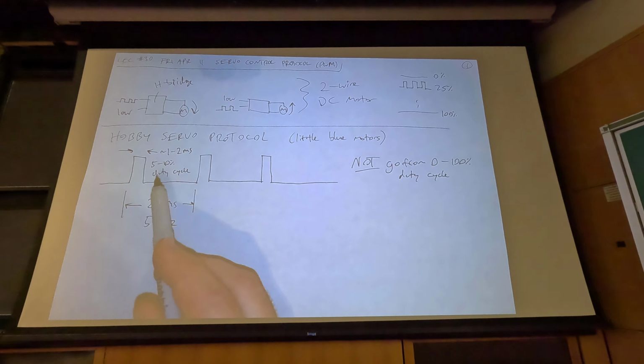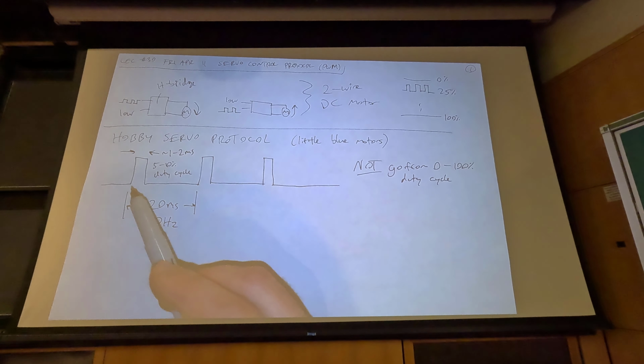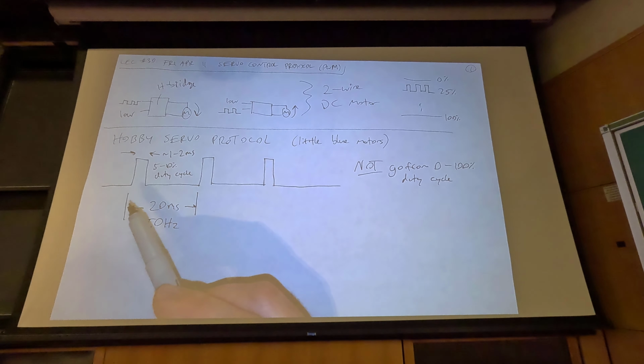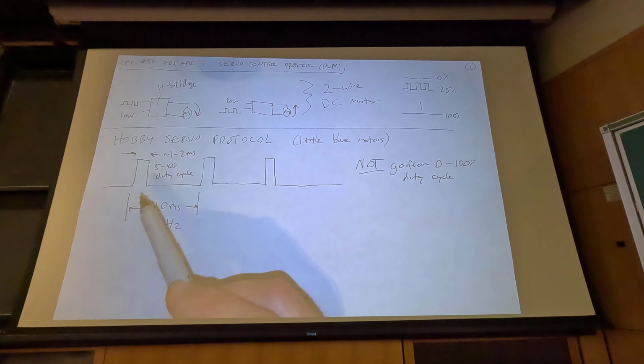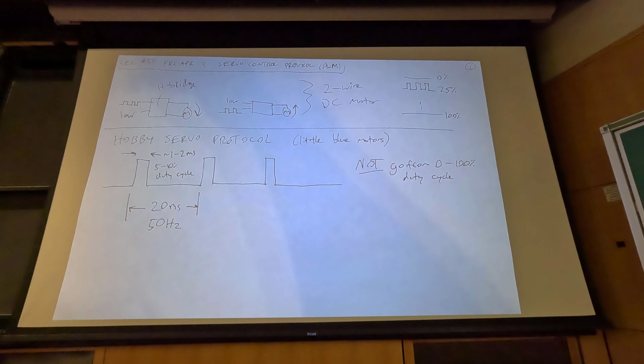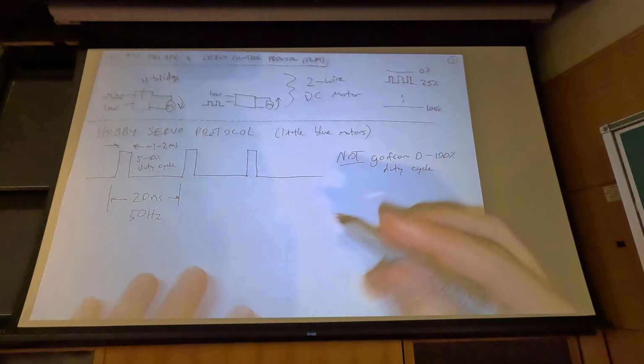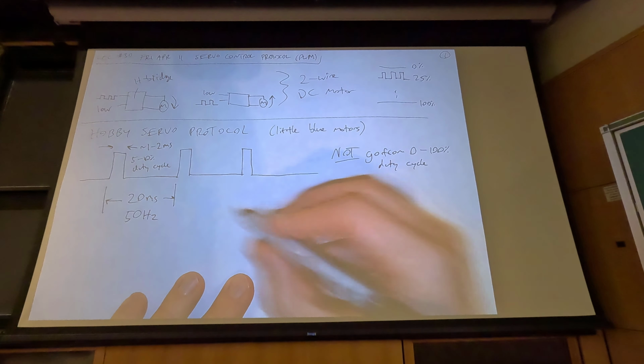This is just an industry standard that somebody made up at some point, and if we were to crack open the case and look inside one of these, there is a tiny little microcontroller, not as big as the one on the Arduino, that is converting this pulse for the positional servos to an angular output. There's also a little potentiometer for the positional ones in there, measuring the angle. There's a feedback circuit that will control the angle. So this is corresponding for that pulse.